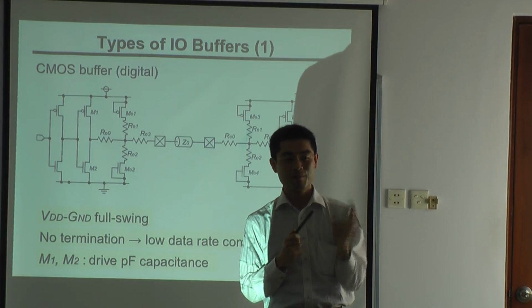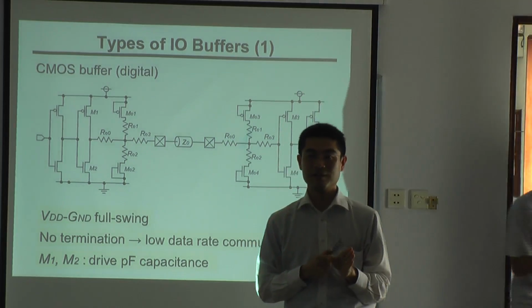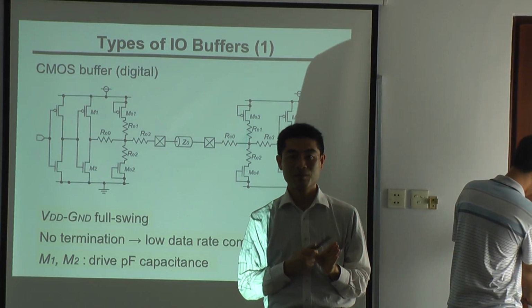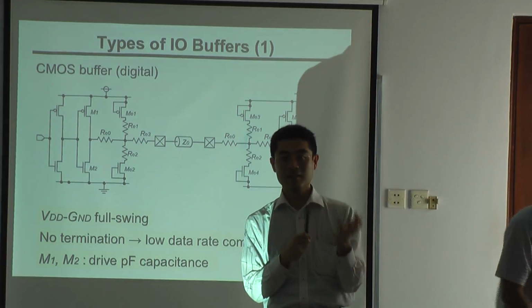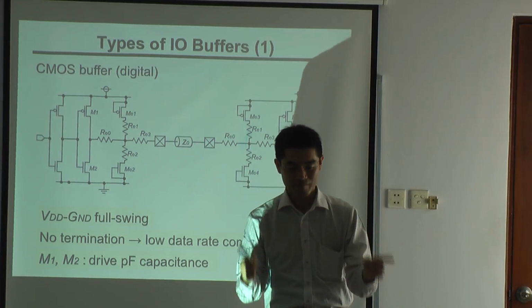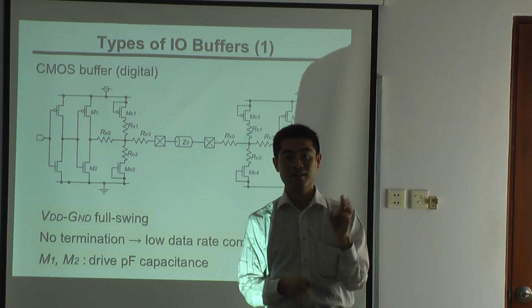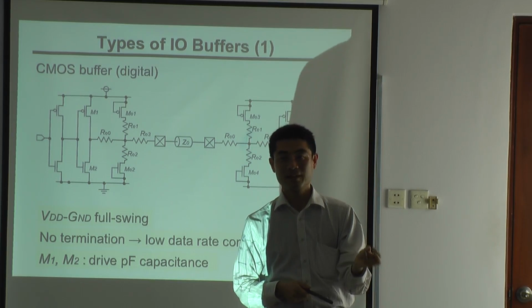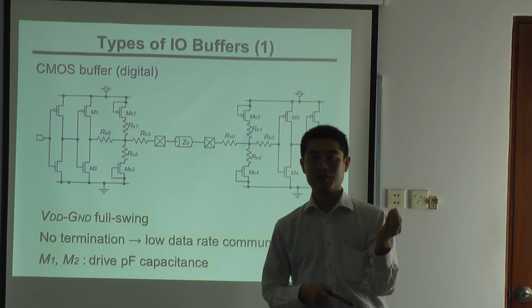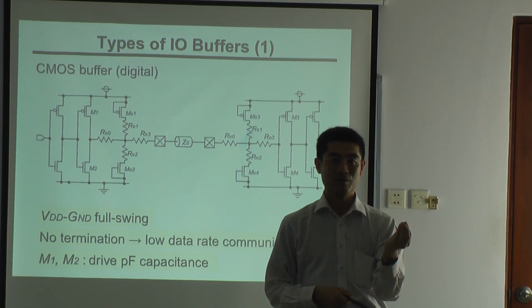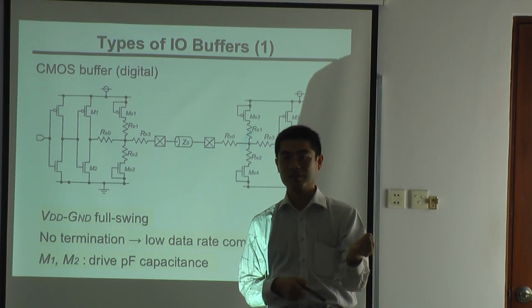The RF part is difficult to protect with ESD. So sometimes the specification sheet says this is an RF part, and you have to take much care, because it has no ESD protection.